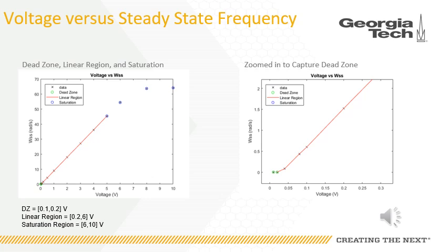We've indicated the dead zone to be within these bounds because the angular frequency at this set voltage is near zero, and it does not increase linearly with voltage. As for the saturation region, the angular frequency levels off and is also not influenced by the increase in voltage.